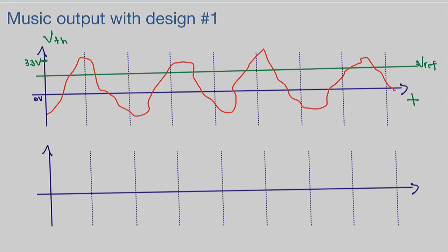What we want is to see what's happening in the speaker. And that's where we are looking at the output. So let me label the output. Our output is going to be like this. So if I have the out here, we set our limit to be plus 5 volts, minus 5 volts. What does that mean? That means that when our signal here is lower than Vref, the op-amp rails and our signal goes to...